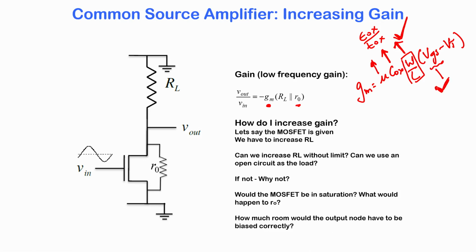We cannot make it greater than the maximum supply voltage used for the technology. And what about Vt? We cannot play around with Vt too much because it is the foundry that decides the dopant concentration, the flat band voltage, etc. So, these are not things that we can play around with, but the aspect ratio and VGS are definitely something we can adjust.